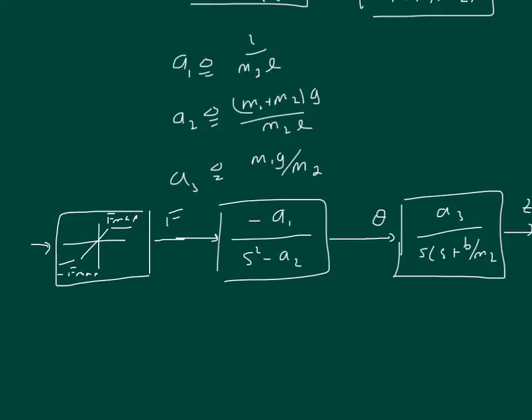It can't get above F max or below minus F max. If the signal is in between those values, it just passes through the saturation block, but otherwise it's clipped at plus or minus F max. And the maximum force actually determines in many ways the possible performance of the system.